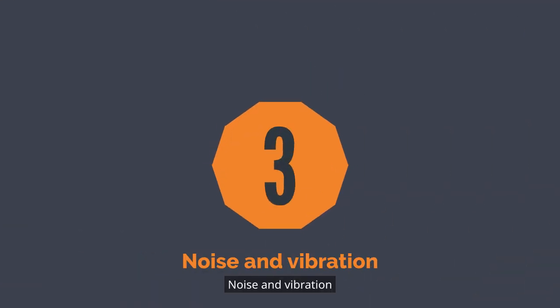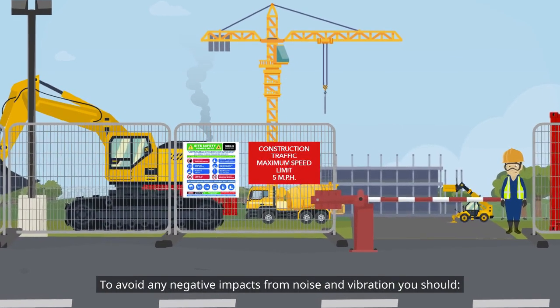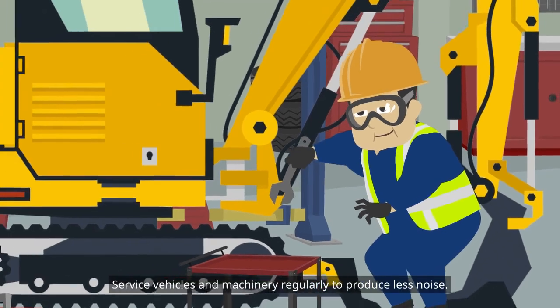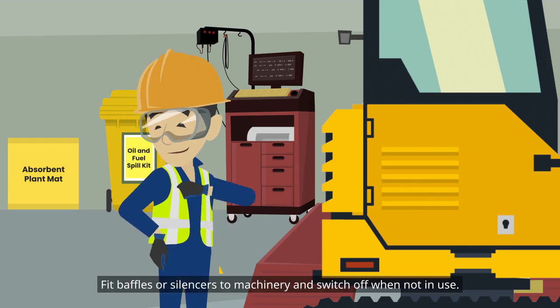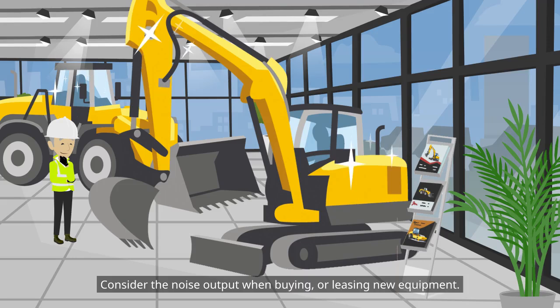Noise and vibration. To avoid any negative impacts from noise and vibration, you should install solid panel fencing around the site to screen the sources of noise. Service vehicles and machinery regularly to produce less noise. Fit baffles or silencers to machinery and switch off when not in use. Consider the noise output when buying or leasing new equipment.